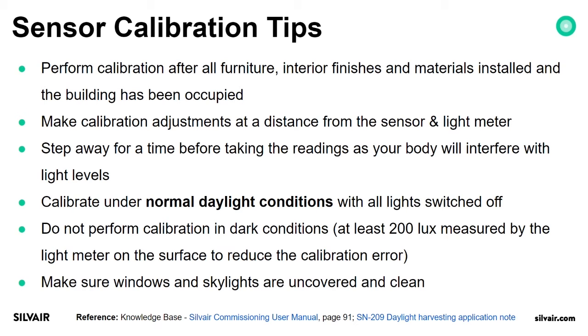So perform calibration after all furniture, interior finishes, and materials are installed and the building has been occupied. It is a very common mistake that installers hand off the project as fully commissioned, even with daylight harvesting, and then the building owner is moving materials around afterwards.